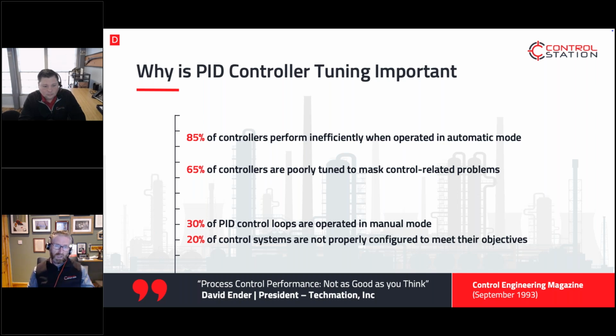Bob, do you want to take those higher numbers? And I'll add into it. The idea that controllers are not designed appropriately for their objectives drives into that top metric there, which is they're performing ineffectively in automatic mode, which means they don't have the right kind of design.